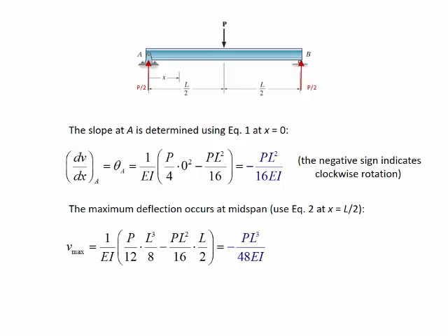So for instance, on the first term, we would have x cubed, so it would be L cubed over 8. That in itself was not a Macaulay function. But if you look at the second term that would come here, x is equal to L over 2, so therefore we evaluate that function. It would be L over 2 minus L over 2. It goes to 0, so we don't have it here.